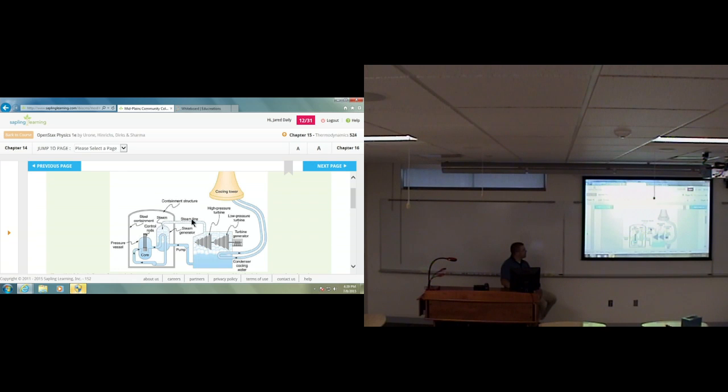But anyway, you get low radiation steam out here that is easy to shield, and you put it through the turbines. The turbines turn. As they turn, the gas cools. It turns back into a liquid, and it goes back into here to get heated up again. You also have to have another cooling method because the steam gets so hot that you need to cool it even more in order for it to turn back into a liquid so you can put it back in here.